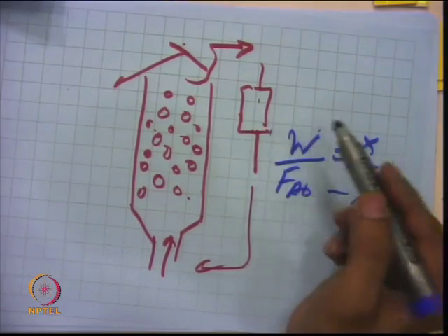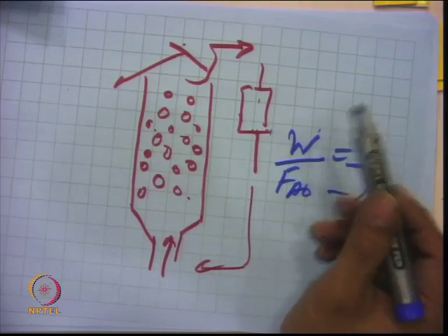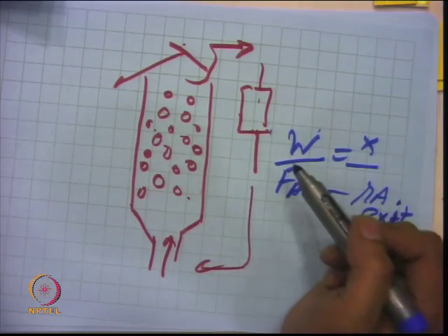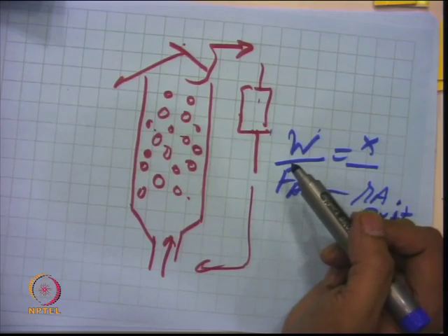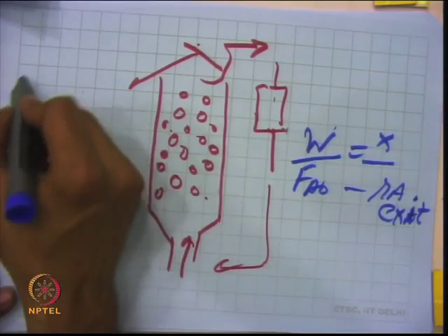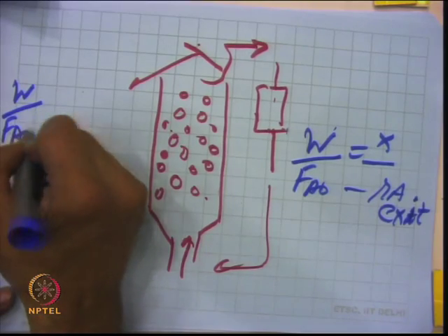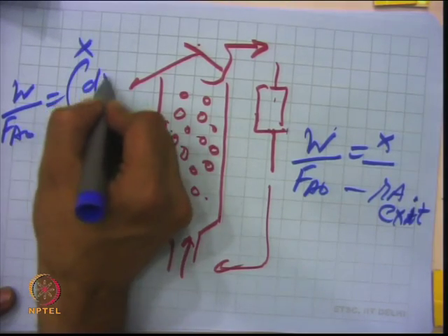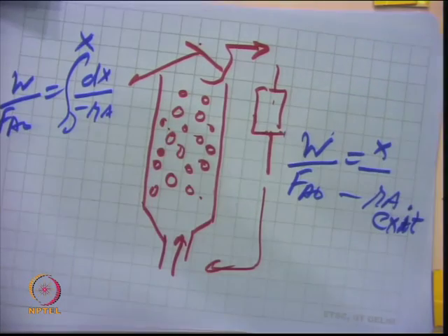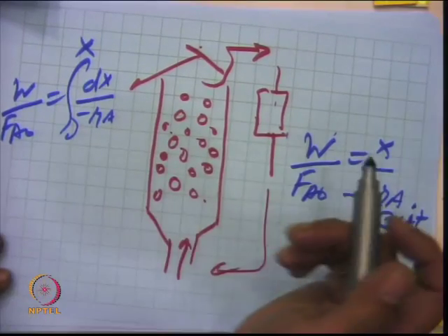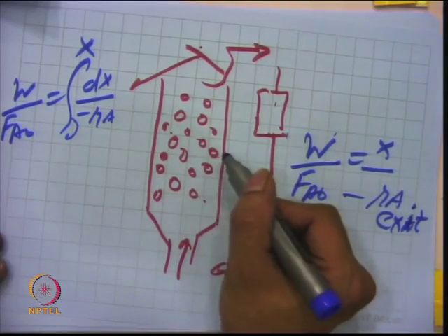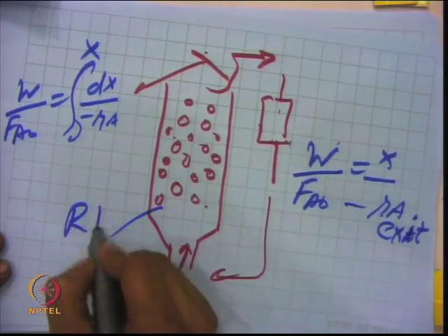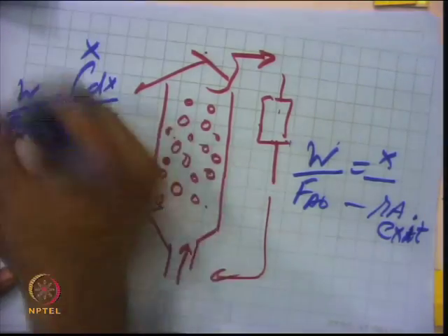So, it means the size of a fluidized bed reactor will be higher compared to the size of a fixed bed reactor, because a fixed bed reactor behaves like a plug flow reactor, which we have discussed yesterday. So, you are calculating the concentration, and that is nothing but an infinite number of CSTRs placed in series. So, in general, when we do the actual fluid bed reactor, we have to study the hydrodynamics. We need to find out the RTD, residence time distribution,